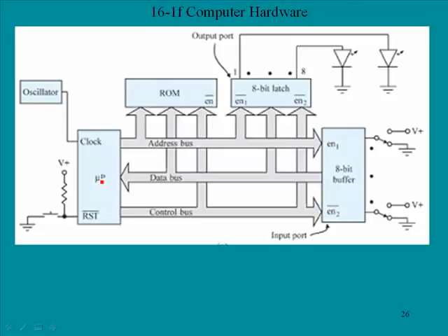Upon decoding the instruction, the microprocessor must obtain another byte to determine which device should receive the data. Therefore, we increment the program counter and again gain access to memory. This time, 2 comes down from the data bus, and we hold it in a temporary latch.